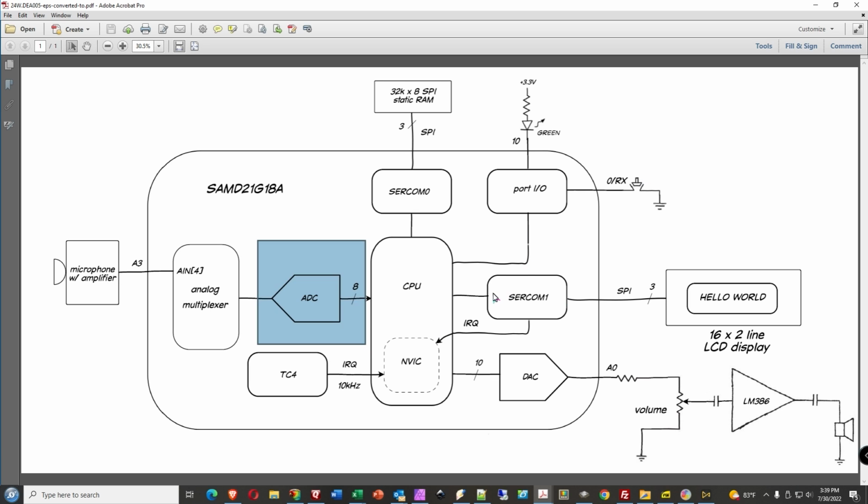The way the system works is there is a front end FSM, and that's the while loop that you think of in Arduino, the main loop, and that is monitoring the button, controlling the LED, and telling the interrupt service routine what to do. The interrupt service routine is doing all the data acquisition. So the finite state machine sits in an idle state, waiting for the button to be pressed. When the button is pressed, the finite state machine begins timing how long the button is down. If the button is down for at least 1 second, it flags the timer counter interrupt to begin recording.